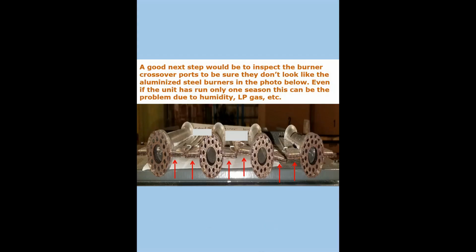I know it's 4 screws taking the manifold off, but if you're sending gas up there and you hear the gas, but it won't light, or one burner lights but it doesn't cross over to the next one, you're plugged up. And you're going to have to clean up them burners as best you can until you get the new ones, if you can't get the new ones right that day. Usually you find that in the wintertime, and people want their heat.